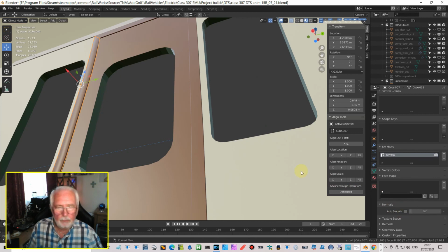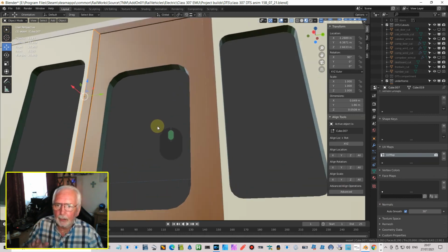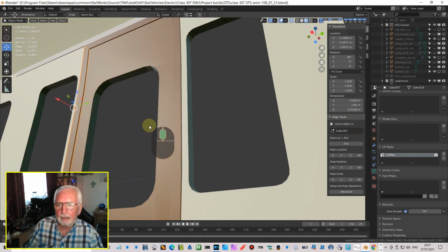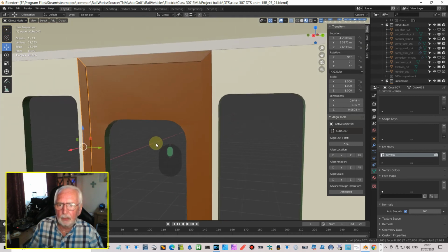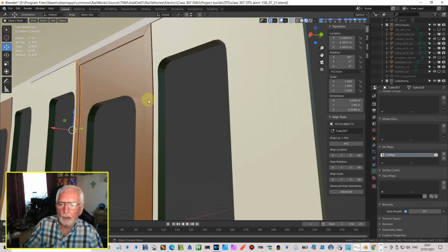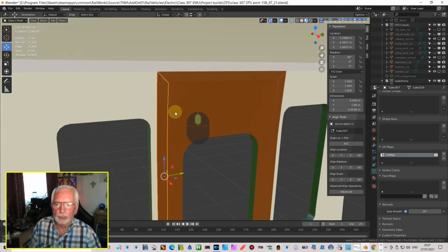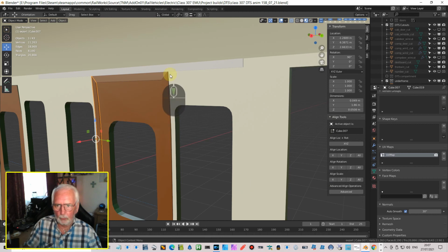Of course, if you want the roundness, then you can just increase this auto smooth angle and you will make it look rounder, but that's fine then. That looks okay, that looks nice there. The bevels there give it a little bit of a chamfered edge there, a little bit of a beveled edge, and makes it look more real. So let's do the same with this one.